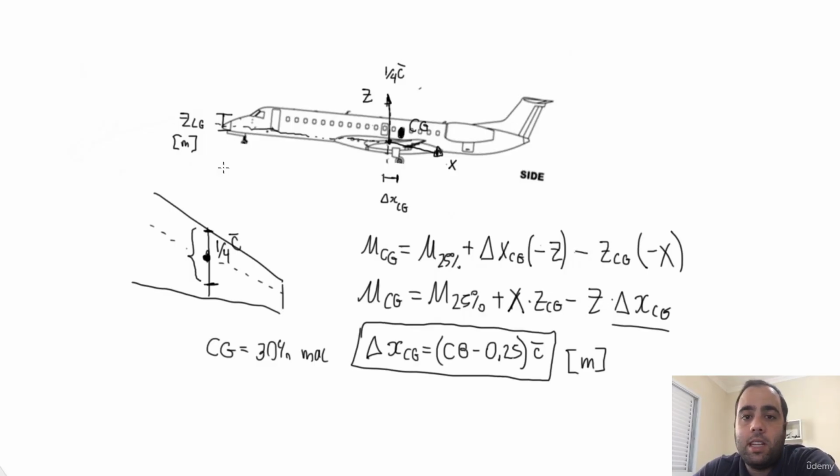So now we just do the same thing for the lateral coefficients, for the rolling and yawing moments. So just correct them, and remember, when we work with those moments, we also have the YCG. Usually we're going to consider that the YCG, the lateral CG of the aircraft, is balanced, so it's going to be 0. It's going to be right at the center of the aircraft. But for the ZCG, as we saw, we do not have that. So let's check the other ones.